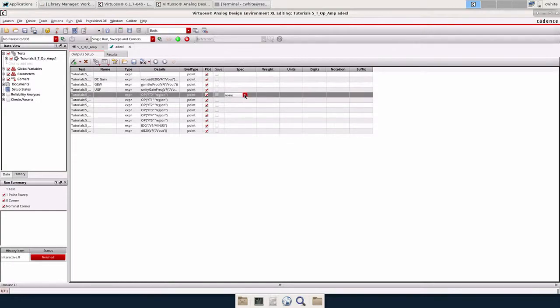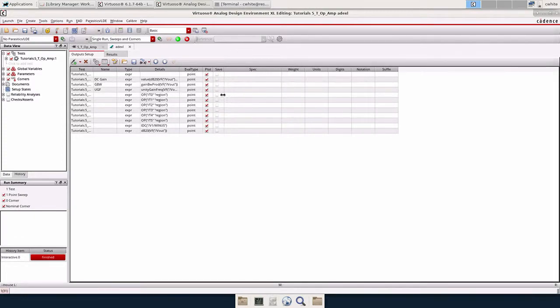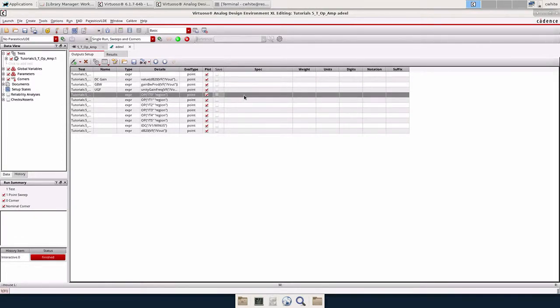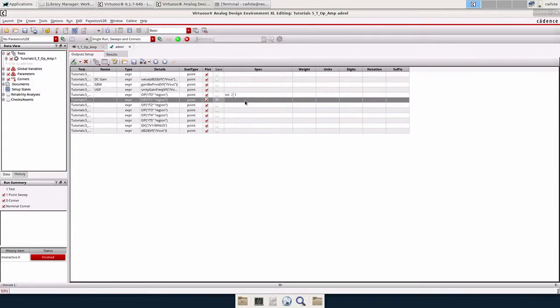For the transistors, we want to be in saturation, so I'll do a tolerance specification. We'll do 2 because we want to be in saturation, which is region 2, and then I'll do a 1% tolerance. I'll basically just repeat that for all of them. Okay, that wraps those up.